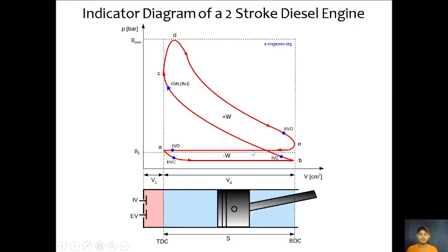The piston moves up, pushing the exhaust outside, and then the intake valve opens. So both exhaust valve and intake valve are open at this point, and the fresh air will push the remaining exhaust out of the combustion chamber. It is what we call a valve overlap for 4-stroke engines, or scavenging or flushing in other terms for 2-stroke engines.